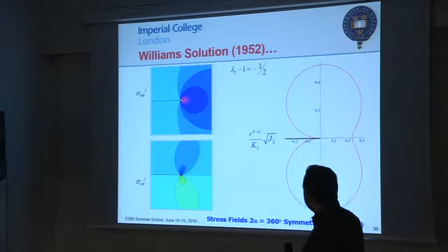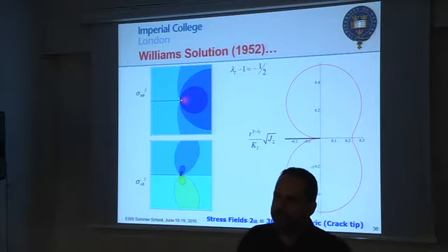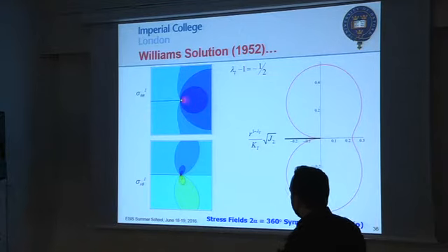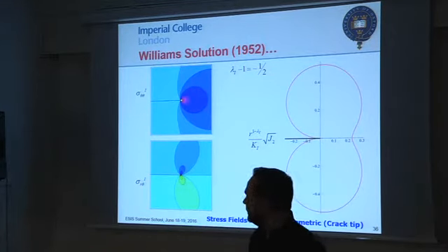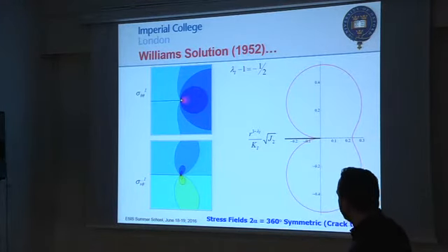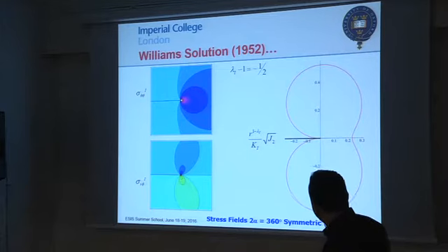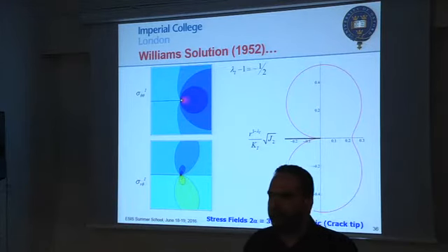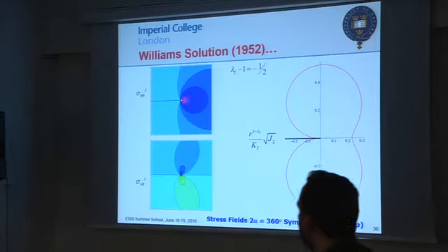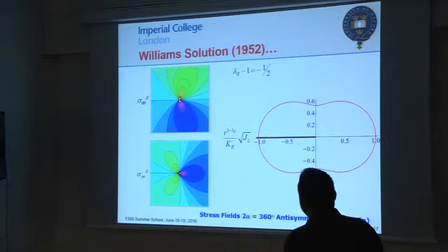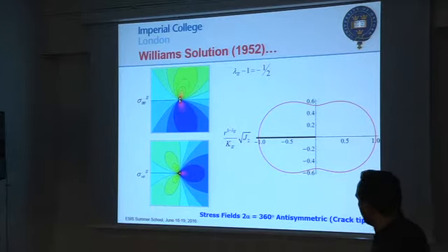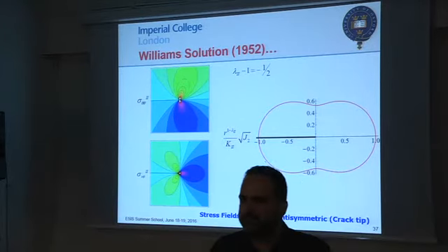And if I do the last one, if I go all the way down to a crack, alpha equals 360 degrees, you obtain what you already know, the perfect solution for a crack, which is lambda 1 minus 1 equal to minus 0.5, and the square root of J2 surface looking exactly like that. Those lobes are the typical lobes you see in a crack solution, and the mode 2 solution having exactly the same singularity, showing a square root of J2 plot of this shape. Yeah?